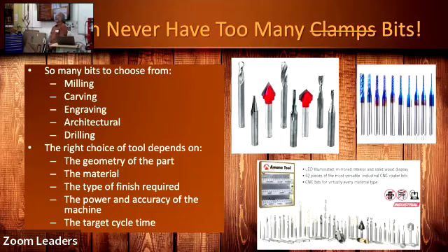For the rough cutting, you have to figure out when you dictate the tool path, if I use too big a diameter of a bit, because I'm taking a lot of material, it might go past. So if you use too big of a bit when you're doing a rough out, is it going to overstep the boundary? It won't. The software will set the boundary based on the diameter of the bit you're using.